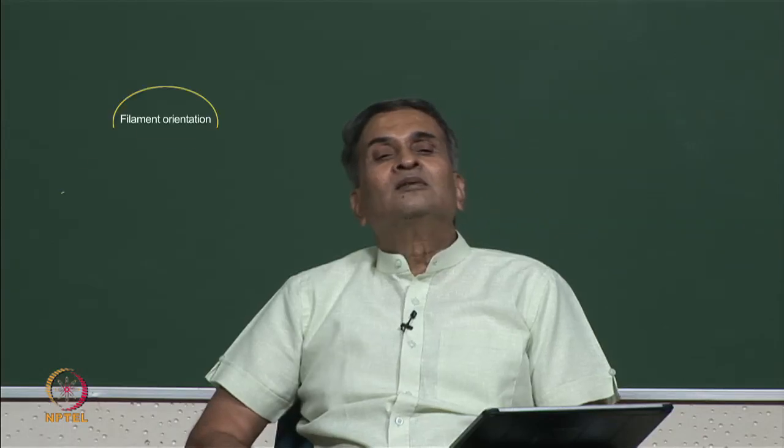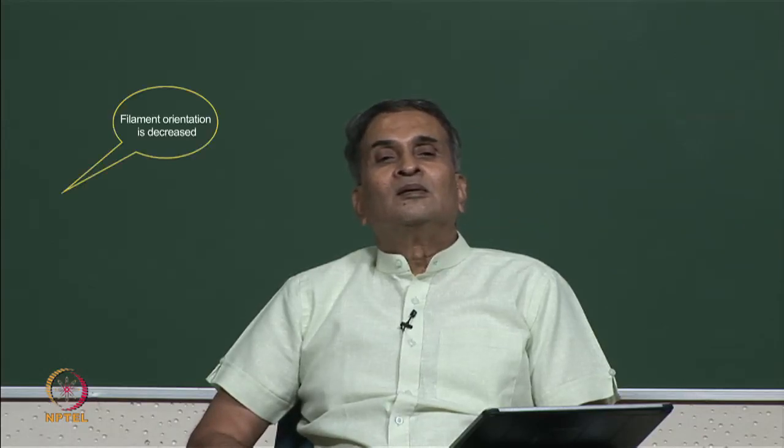So, why do you believe that there is no change? Oh no, there is a decrease, or was it an arbitrary nice thought? Yes? Filament orientation is decreased. All right. So, one answer has come that the filaments after air jet texturing are not parallel to each other. In a fully drawn yarn before texturing, all the filaments were parallel to each other.